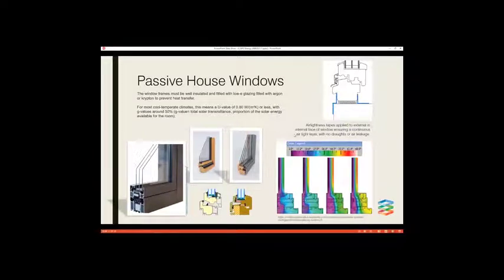So looking at how the window is installed in the wall system is important as well. Quite often people will say the window has to be installed in the insulation layer. Okay, so they're talking about big cool climates. But here in Australia, our wall systems are much thinner. So we actually have to look at how all of that works together. Being aware of how those things work together is super important.